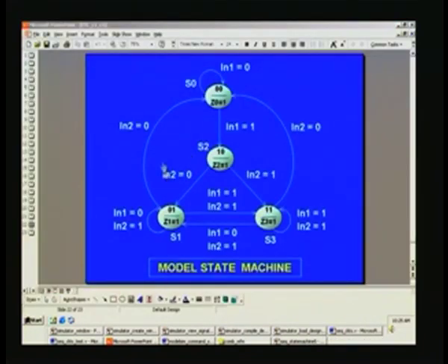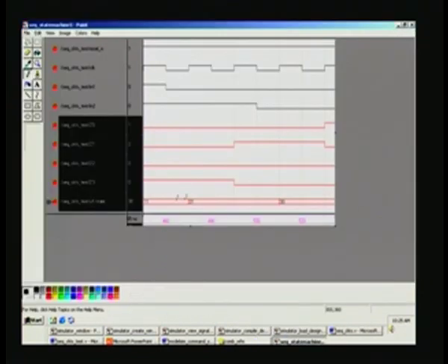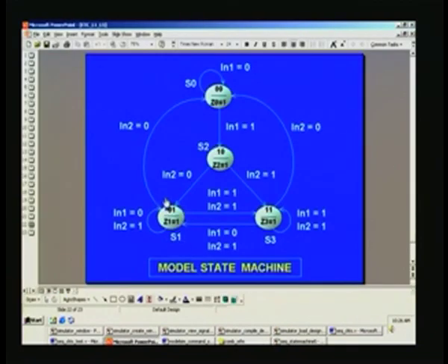I think this is the path we have not covered, I suppose. Let us see whether it is. So, let us say from S1 to S1 state. And then from there it is returning to 0 state, and let us see the condition here. And, so, what is this here? 1 1. So, input is 0 1 here. So, in 1 1 state 0 1 we have to look into this one, is it 1 1? Yeah, it will go to S3.